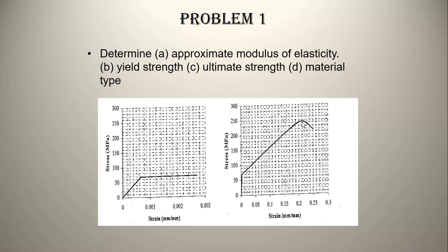Yeah, the second one. So there, if you look at the column for modulus of elasticity E, and you look for one which has approximately 100 gigapascals, you find that there is none with exactly 100, but the closest one is 101. For this E equal to 101, you also check the yield strength, it is 70.